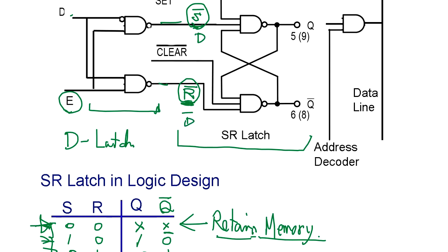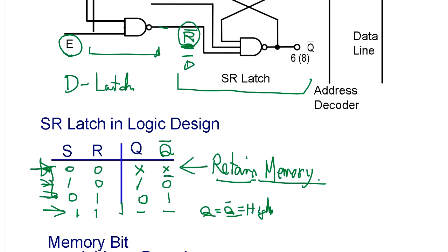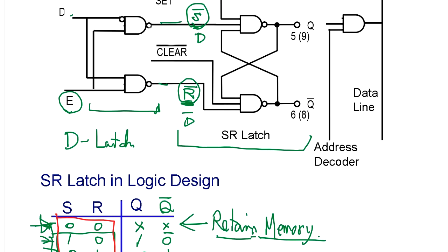So we're talking about this area. Okay, so D-latch uses only this state. Okay, so it's guaranteed to be logically correct. So that's a D-latch. So D is for data. Data comes in. And enable means enable storing the data into Q and Q bar.